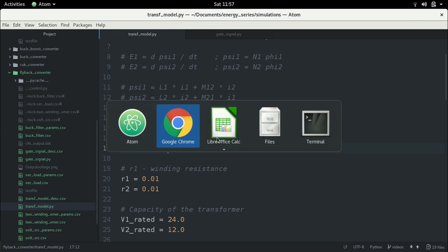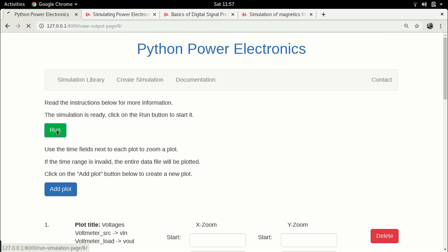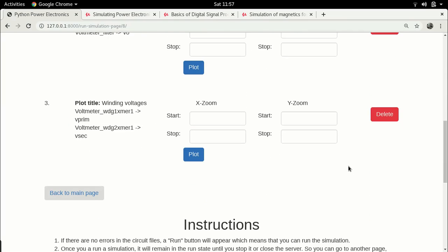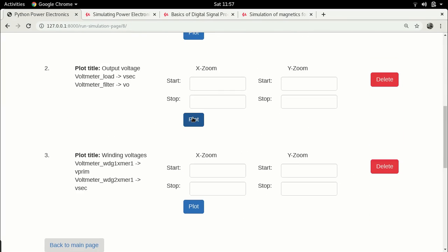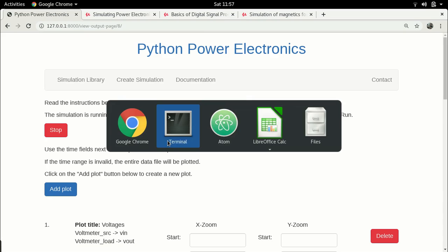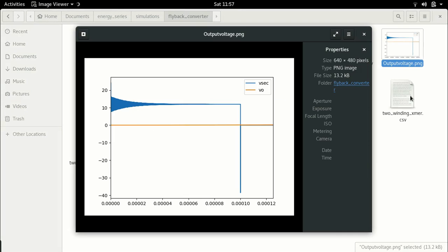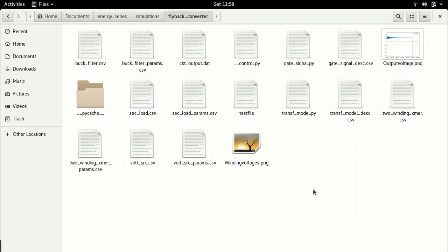So let us go back and let us now run this simulation. So as always, let's go to the console, make sure there is no error, there is none, so we should be okay. So let's go try again to plot the output voltage. It may take some time, which is okay. And you see that the result is much faster, and this is the impact of having a smaller integration time step, right? This is how much faster your simulation runs. Now, I think I may need to run it once again.